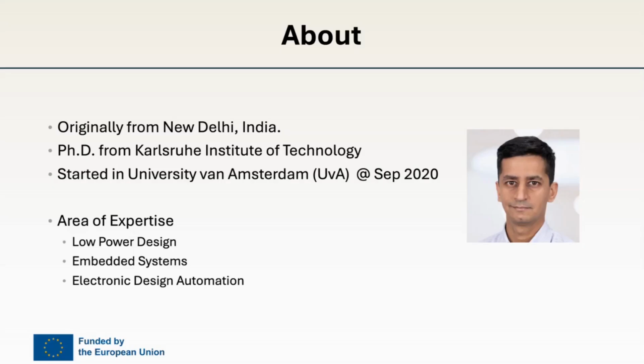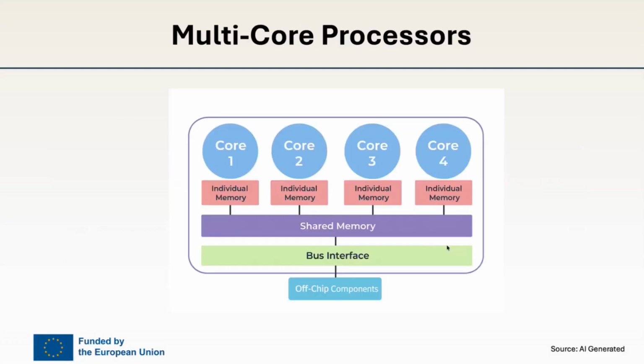So today I'm going to talk about how to model the mean time to failure for multi-core processors that are resistant to core failure, which basically means that they can still survive if one of the cores or many of its cores still dies out and so on.